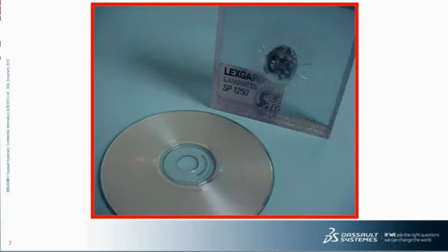So you take polycarbonate, very low molecular weight, very high flowing material, you can make a DVD. You take a very high molecular weight polycarbonate, very stiff flowing, doesn't like to flow into a mold, you can make bulletproof glass out of it. So it's just important to understand those kinds of things about the basic plastic material before you go ahead and design a mold.